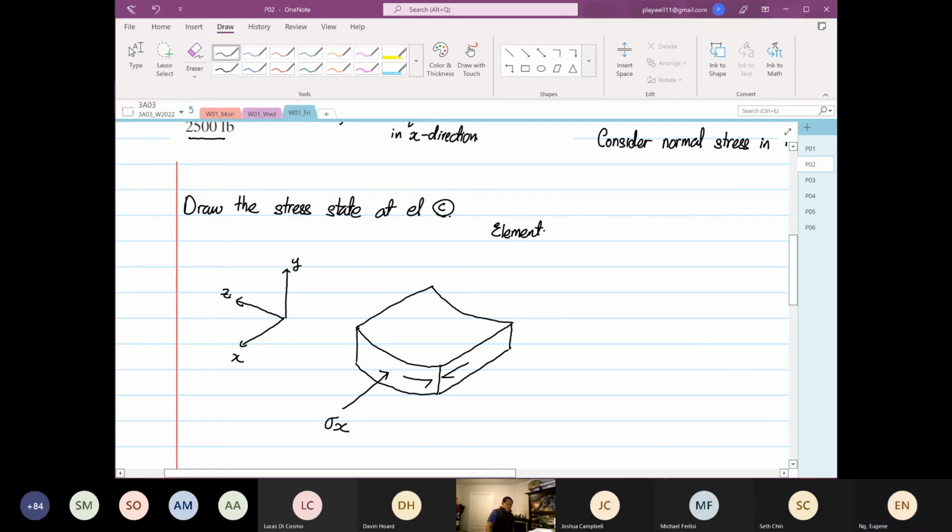Then we only have these stresses. So what do we call the shear stress I've just drawn? This is shearing stress. The intersecting plane is on the x-axis, and the shear stress is in the z direction, so shear zx. I will teach you labeling all this when we reach that chapter.